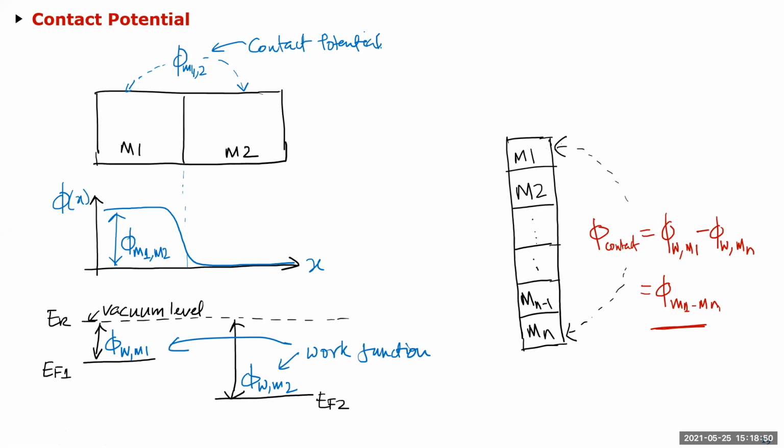And so for example, let me take an example here. Let's say I take an example where I have a P plus and n plus, right? You find the contact potential, let's say it's 0.45 volts. Now you take a P plus oxide n plus, it's still 0.45. Now you take P plus, metal, n plus, still 0.45.